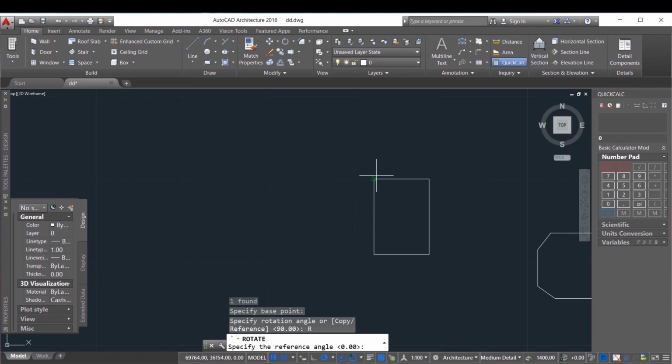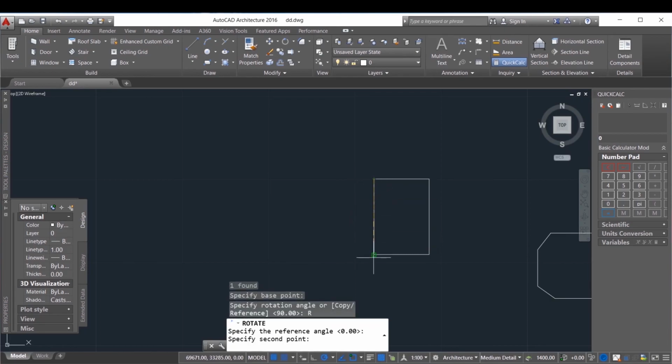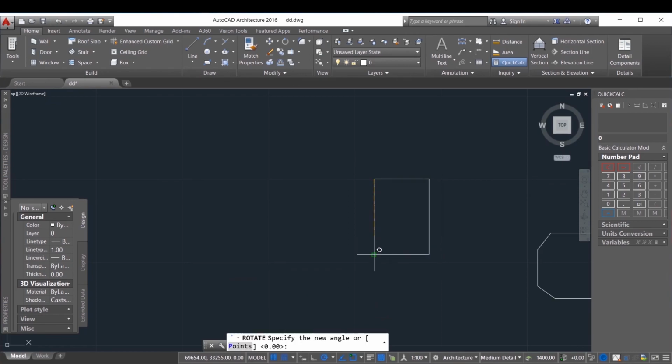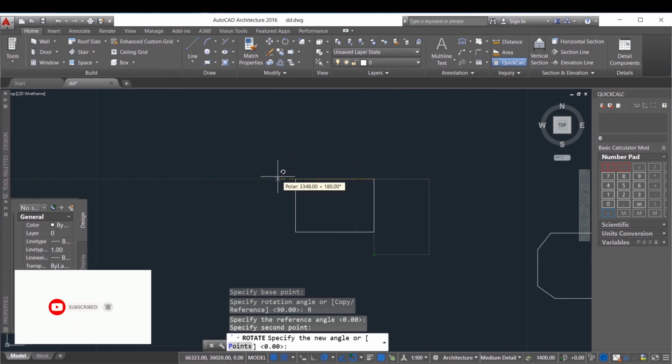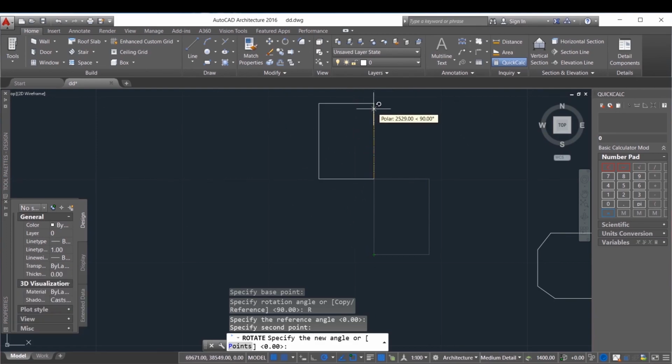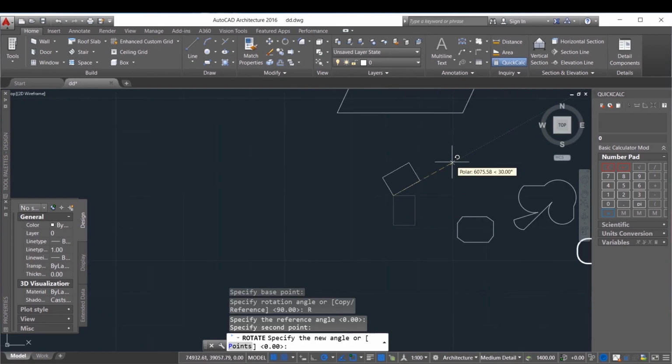You first click your first point, then you click your other point. So this time around, you hold 2 points in rotating the object. So you rotate the object to the position or the orientation that you want. Then you drop it by left clicking.